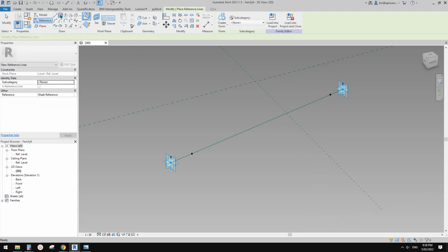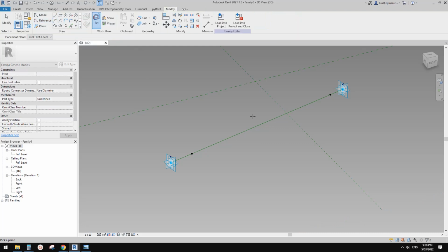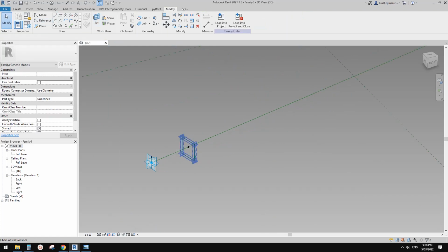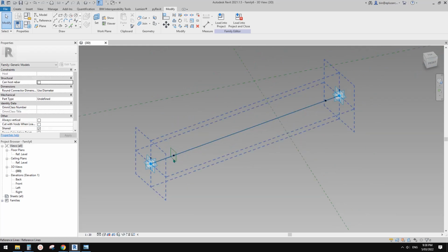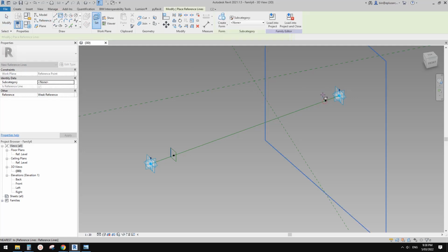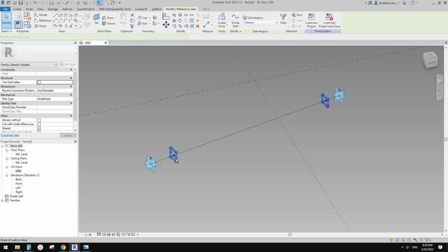And then I'll just place a profile. So reference, I'll use a rectangle and draw on work plane, set work plane, pick this, and I'll just draw a shape. I'll skip the dimension for now because we're going to adjust this. Okay, so one here. Actually, let's do another one here.